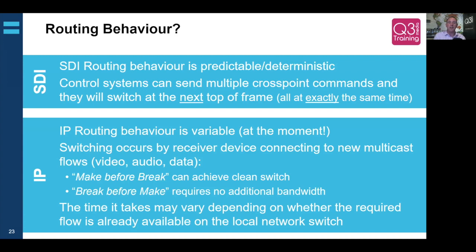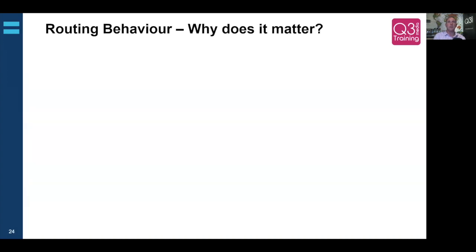everything up. The fact that we're passing flows in 2110 as video, audio, and ancillary data as separate flows, again, just means that there's more to go on, which only makes things worse for the kind of delays involved in that IP fabric and how long it takes to respond and the receivers to respond. So, don't expect instant switching with IP.